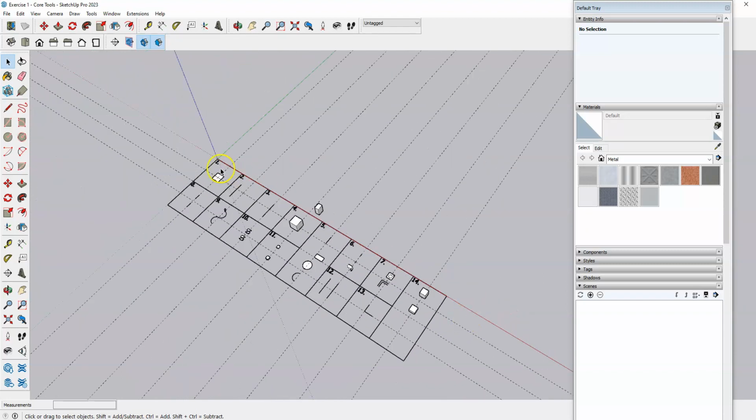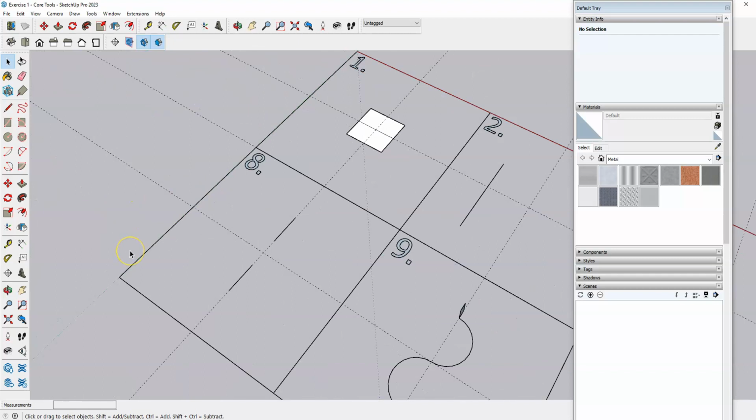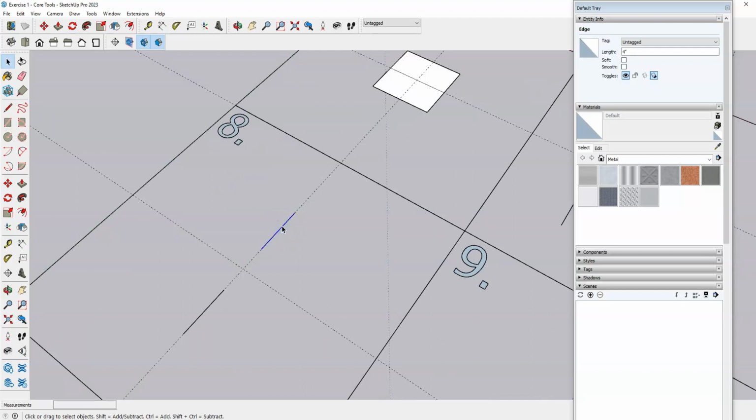We'll move to box number 8, so down here in the lower left corner, and we're going to learn how to use the rotate tool. So rotate is going to look like these two arrows that are in a circle here, and your hotkey for that is Q. I don't know why they chose Q, but they chose Q. So to use the rotate tool, you can rotate an object to any specific angle. So again, here you'll want to select your object first and then activate your rotate tool. So I just hit Q on my keyboard.